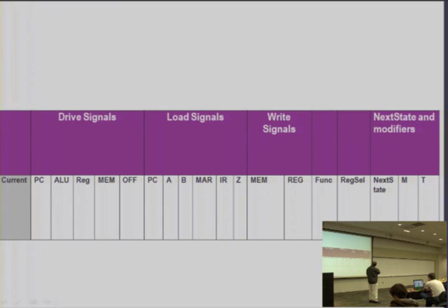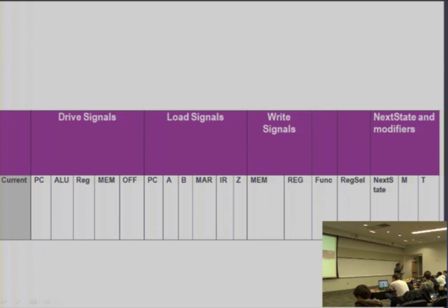But now what we've done is we've also added 2 additional modifier bits, right? And the modifier bits are going to come into effect exactly when we're talking about. That is, we're not going to use it always, right? So under certain conditions, when we want it to be modified, for instance, the last microstate of the fetch sequence, I'll have the modifier bit turned on to say that, well, modify the top portion of the micro ROM address using the opcode bits.